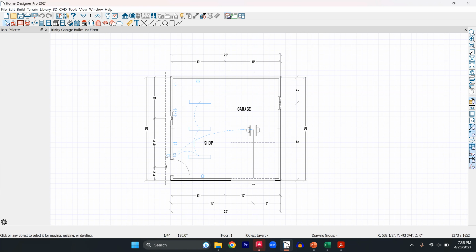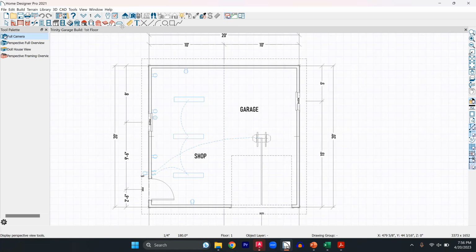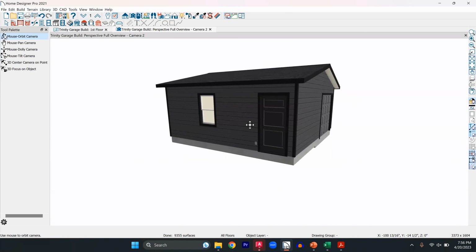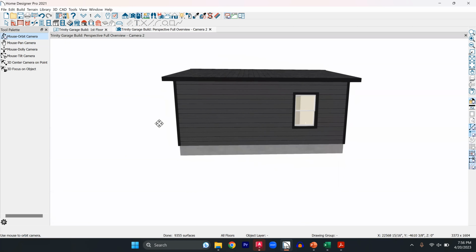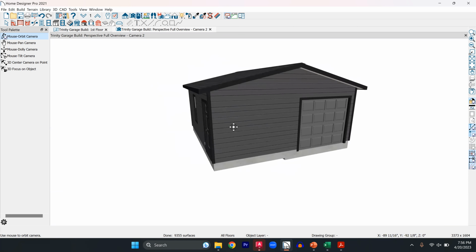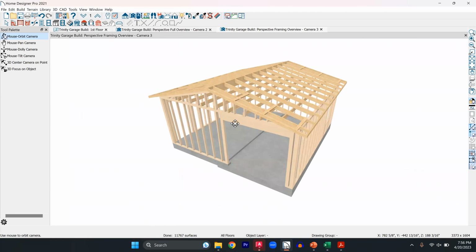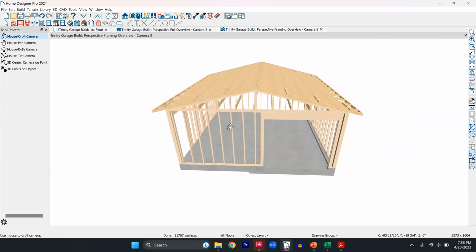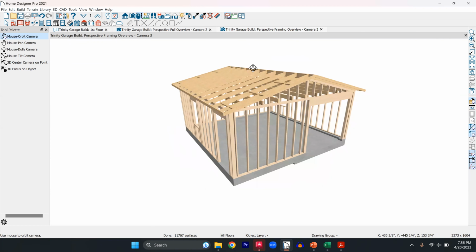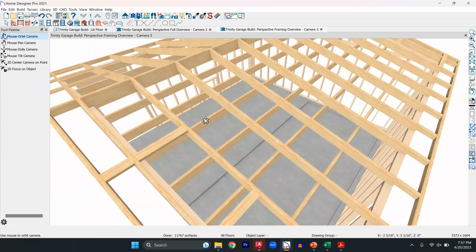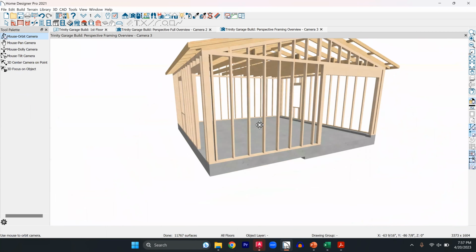All right, so the way I can use material estimates in this program is I have this model generated such that the computer knows that this garage exists. So it's got this in its brain. It does all of its math. It's got all of its 3D calculations going on. If I were to open up the framing plan, it will show me all of the intended wood members and their directions. So this may or may not be how I want to build it. In fact, I know I'm not going to do it this way because the ceiling joists are running the wrong direction. I need them to be parallel with my rafters because of how I intend to solve this structurally.